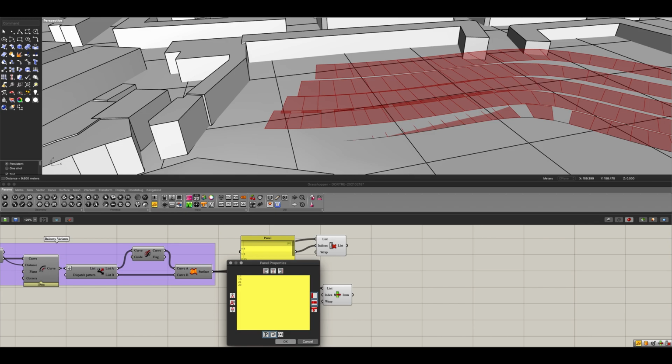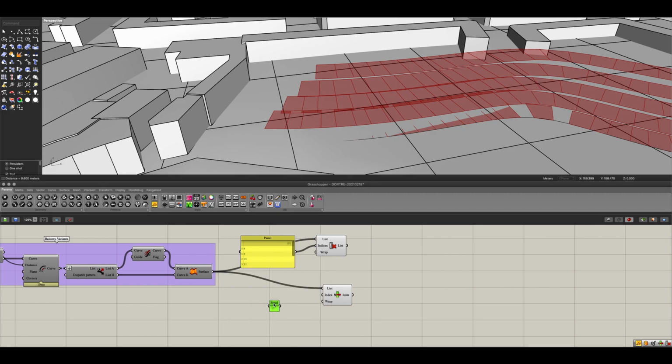Since these values are already separated into odd numbers, you always need to jump a number when you're doing this. So 25, 27, 29, and then as we move on to the next floors, we need to change these from odd numbers to even numbers. So from 29 we go to 48, 50, 52, 54, 56, 58, and 60, like that. Okay. Multi-line data, add it in there.